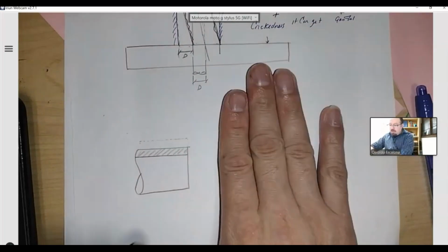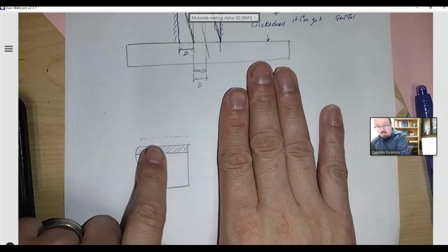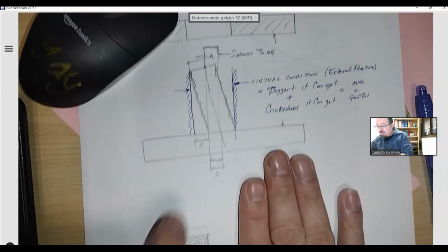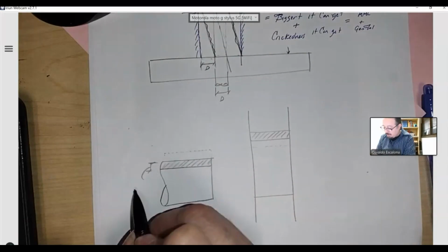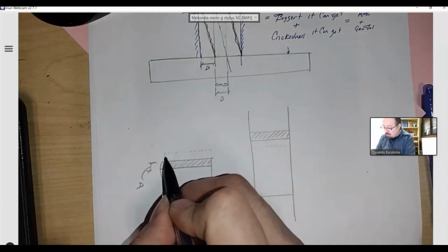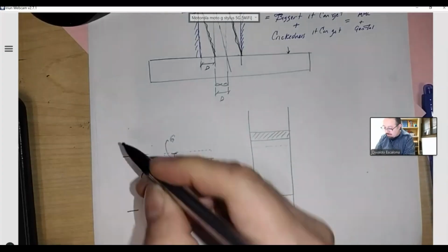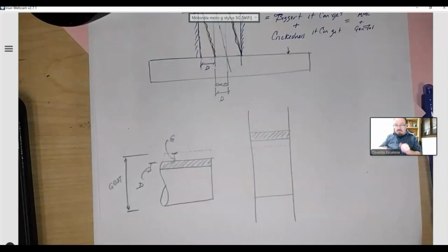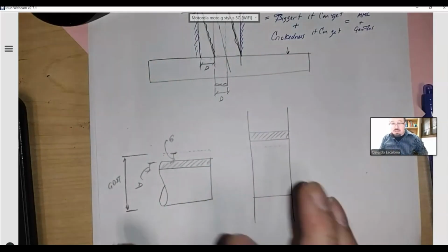So when I have a pin, which is an external feature, my part needs to account for the biggest I can get. And I also need to add a little bit more, and the little bit more is going to be my geometric imperfection. So you actually have two tolerances altogether. One, which is the dimensional tolerance, and two, which is the geometric tolerance. The total thing is what G, D, and T is, pretty much. In terms of features of size, right? Because we're doing features of size, things that have diameters, or things that mate with each other.